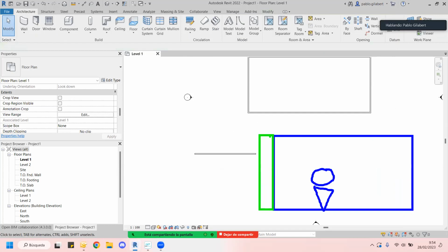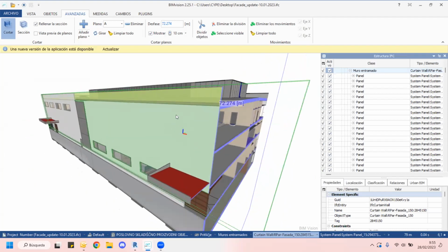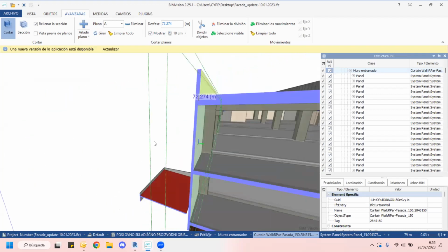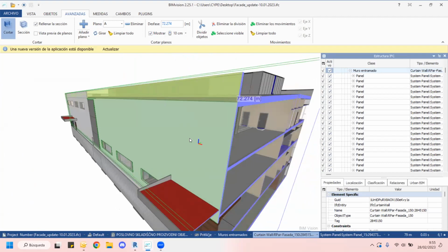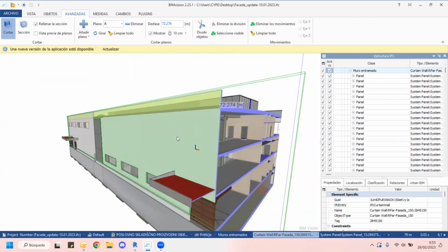If not, we can get this interior wall, but we need to consider, I don't know how to do it, because in Revit you have windows in the interior panel, no? Yeah. So this is a problem of the IFC. And as in the IFC we don't see these windows, we can't interpret them. So we have to solve it.